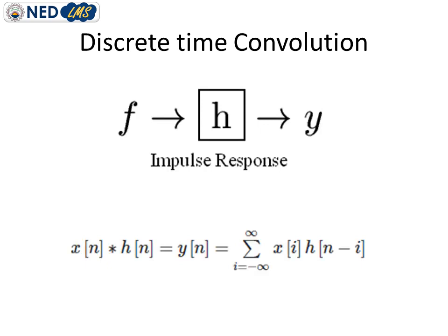Since we know the response of the system to an impulse, and any signal can be decomposed into impulses, all we need to find the response of the system to any signal is to decompose the signal into impulses, calculate the system output for each and every impulse, and add those outputs back together.